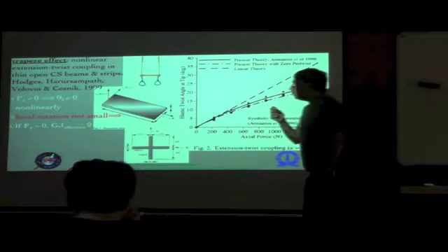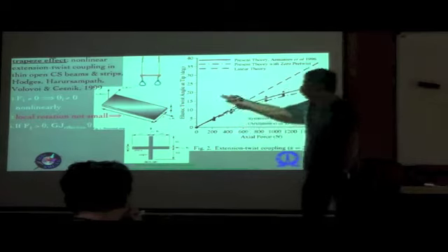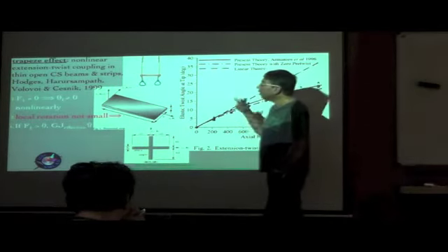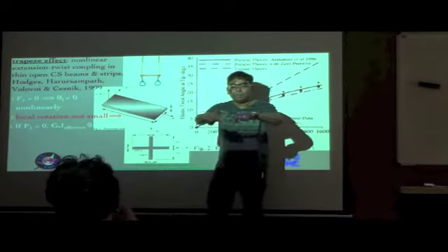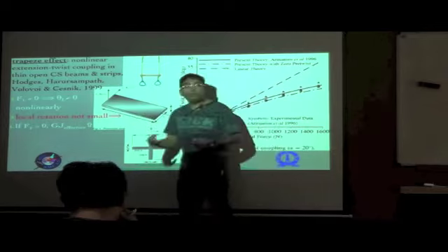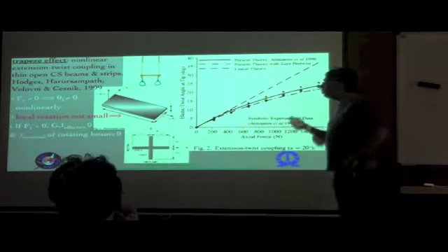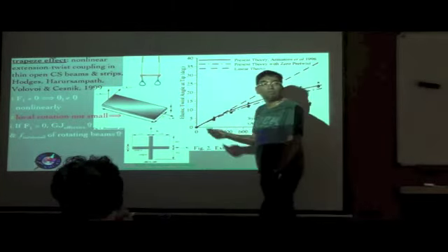Now, there are two cases that we can consider. First, the tensile load, which is what is most common in many of the engineering structures whose examples we discussed. Now, if F1 is greater than 0, as we discussed in the simple situations, the effective torsional stiffness increases, and obviously when the torsional stiffness increases, the frequency associated with it, the natural frequency in